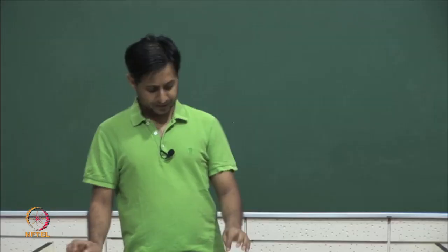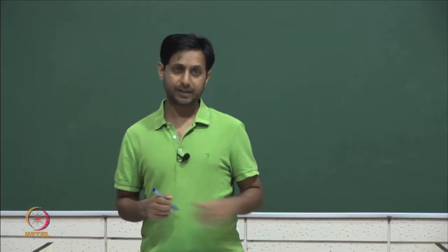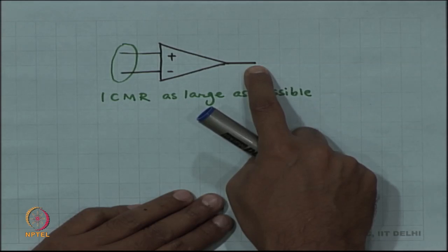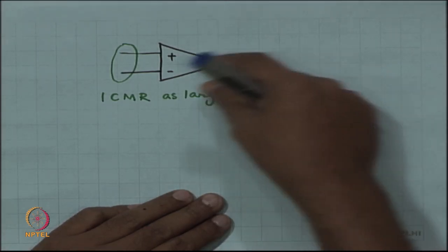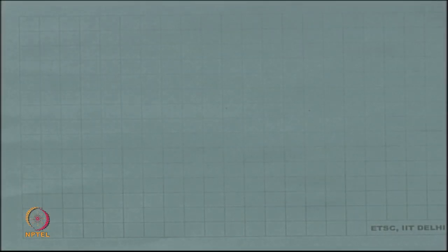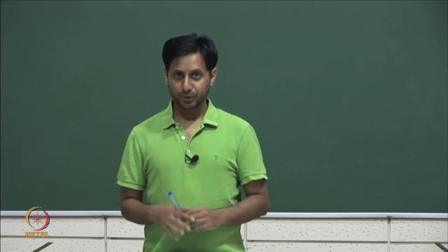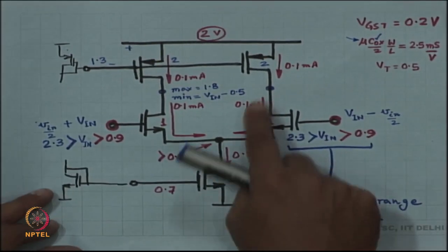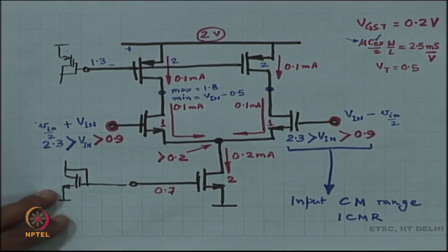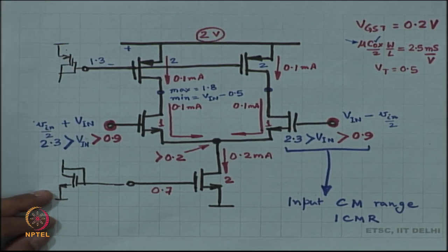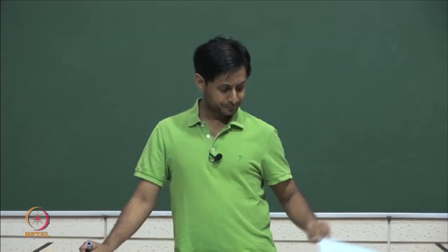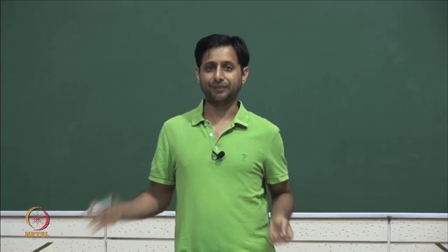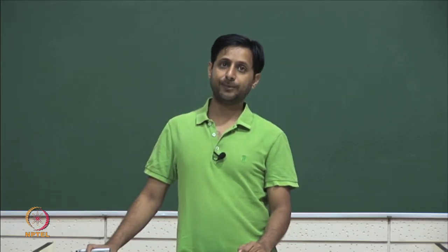Okay. So, there is one more strategy, right. As you see, when you are trying to make an op amp, the output could be single, the output could be double, right. So, you could have two outputs, you could have one output. Ordinary op amp has only one output, right. So, you do not really have to make two outputs like in this circuit. This circuit had two outputs, you do not require two outputs, just one output is sufficient. Okay. So, one other possibility is, can we modify this op amp and get some benefit if I have only one output as opposed to two.